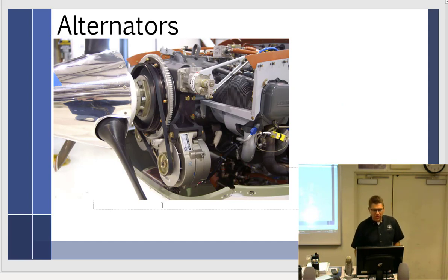By the way, belt tension is usually about a half inch deflection. A half inch. When you put a certain pressure on it right in the middle, it should deflect about a half inch. Okay. But you have to know what that certain poundage is. I don't know offhand. Does the twist test not apply on airplanes? I'm not familiar with the twist test. I've always done the deflection test. That answers the question.